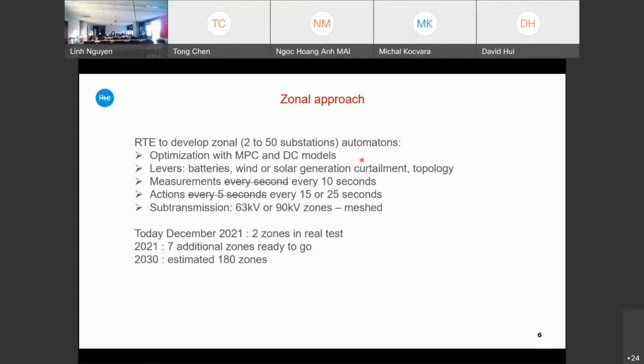So today you may hear about DC grid in some papers, or high voltage direct current, so HVDC lines. It's the fact that the power grid has been running with AC power, alternating current power, for a century already. And now we are putting some direct current parts on it, because for underground or undersea lines, it's more convenient. Here, in this slide, DC model means DC approximation. So this is AC power with DC approximation.